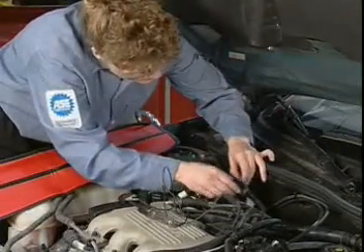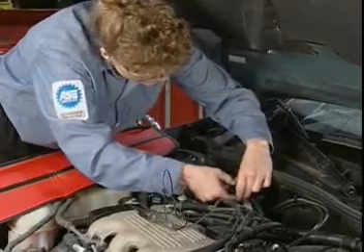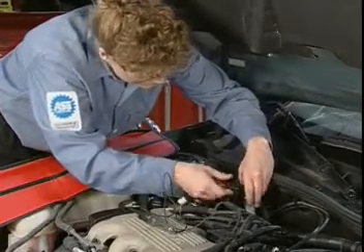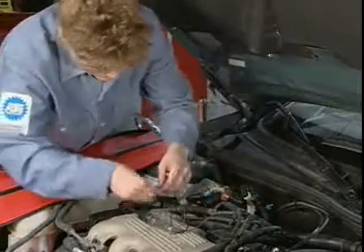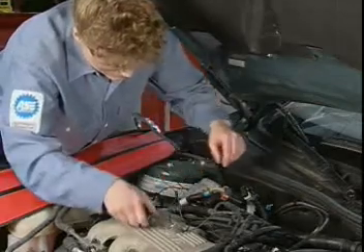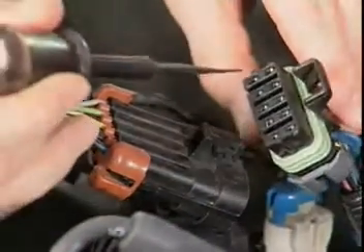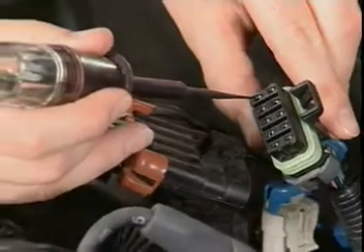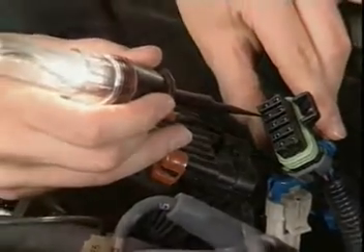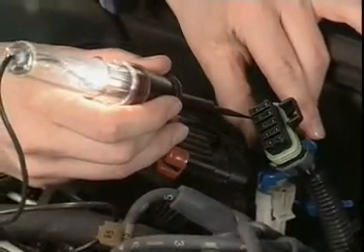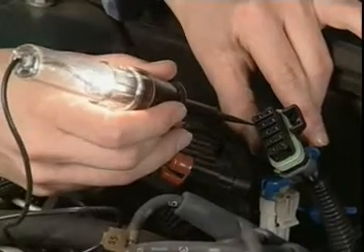There are several methods used to locate open circuits. If the problem cannot be located by visual inspection, use a test light, voltmeter, or ohm meter, beginning at the source of electrical power to locate the fault. Be aware that a test light is generally not used on electronic components unless specifically recommended by the manufacturer.